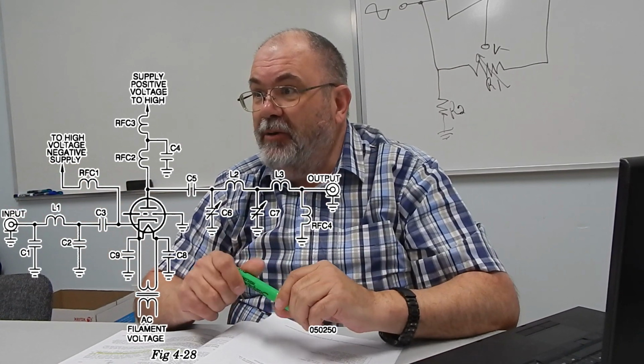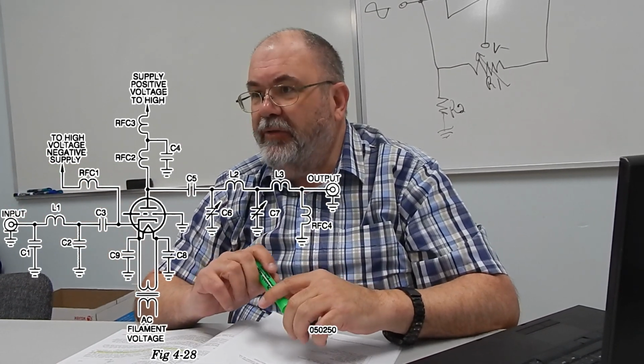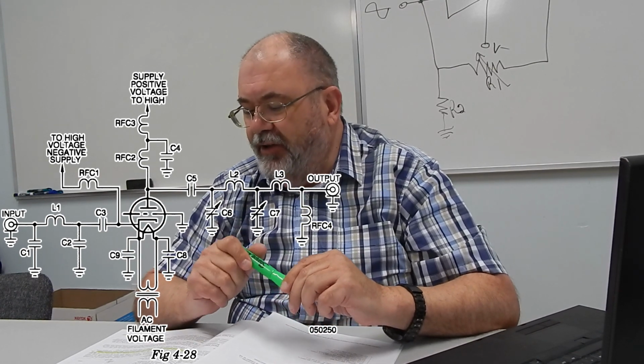And if you go to a flea market and you buy an old tube amplifier, before you even plug it in and turn it on, you take it apart and you make damn sure that that blocking capacitor, that's a DC blocking capacitor, stops that high voltage but lets the RF go through. You make damn sure it's there, because those power supplies are high voltage and high current. They are lethal. Okay, so it's a safety thing.